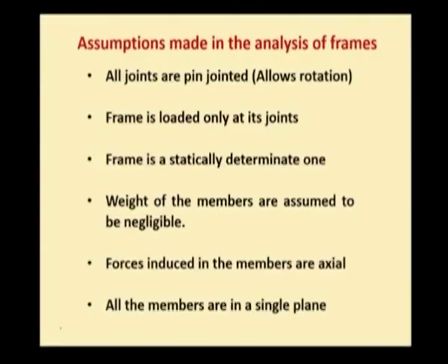Statically indeterminate frames are frames in which the unknown member forces cannot be determined by using the conditions of static equilibrium alone. For determining the unknown member forces, in addition to the 3 conditions of equilibrium, equations in terms of deflections, known as compatibility equations, are also needed. Now, for our study, we are going to see the analysis of only statically determinate frames and trusses.